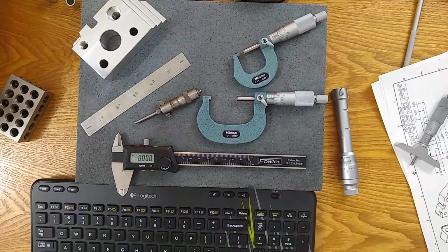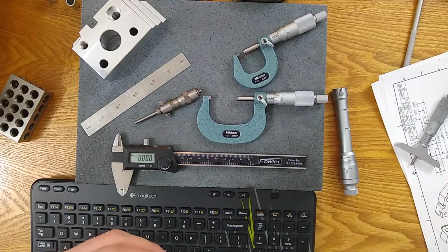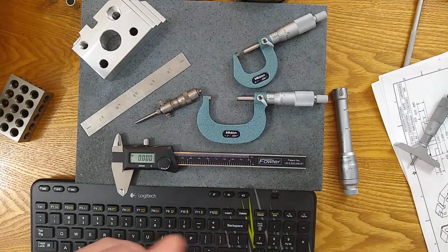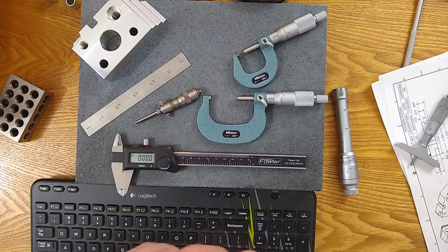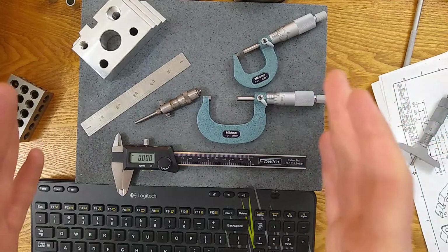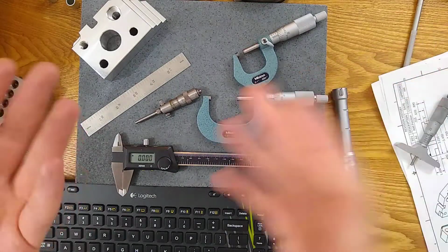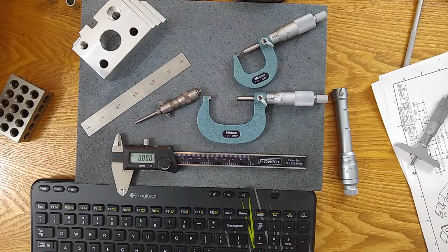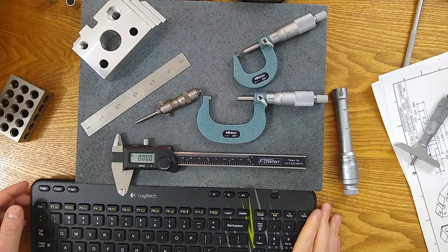You have bigger pieces involved, more travel involved, more accuracy error. But the uncertainty ratio remains constant. No matter the size, it comes down to the resolution. So the uncertainty ratio is helping you choose the gauge. The accuracy is helping you determine if your part is going to be within tolerance based on the accuracy of the gauge. And we have one more.